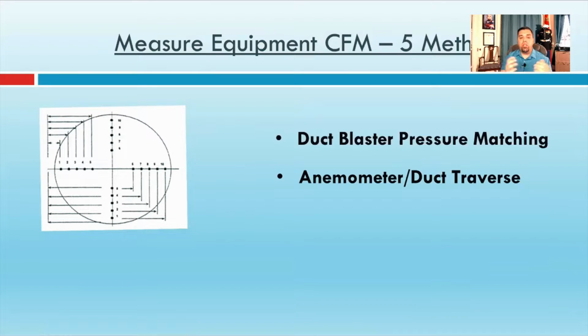So you would do this typically away from any sort of sharp bend, actually 4 dimensions away from a sharp bend, just like your duct design. And you're going to put evenly spaced holes across, let's say, that rectangular or circular duct to measure the total volume of air before any takeoffs. So that one, unfortunately, if you turn your wrist slightly, you could get a completely different feet per minute. So there is a lot of math in that. You'd have to get an average feet per minute and then convert that to cubic feet per minute to get CFM. So that is approved, which is why I'm mentioning it.